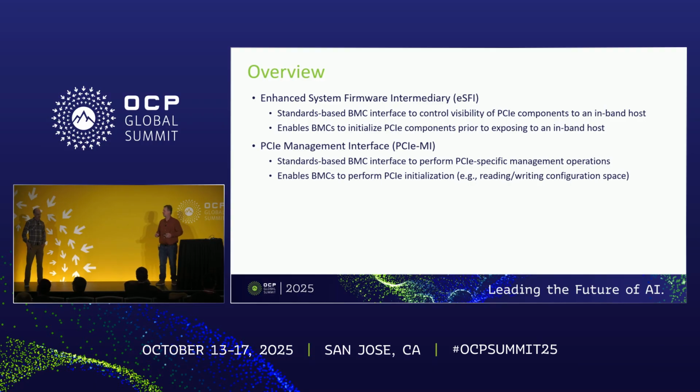If you're interested, Austin will also be having another talk in about 45 minutes that will go into some of the more management-focused aspects. As I go through this, we're probably both going to do some blending of eSFI and PCIe MI. Even though they were published as separate ECNs, in a lot of ways there's coupling: eSFI provides some knobs and manageability control points, and PCIe MI provides the spec-intended mechanism to manipulate those control points.